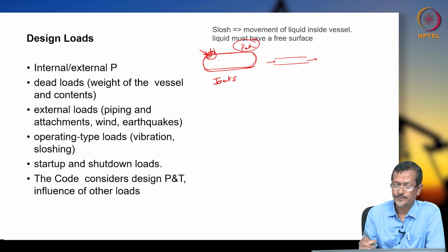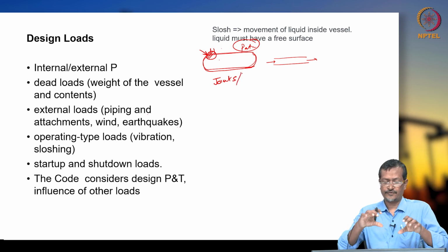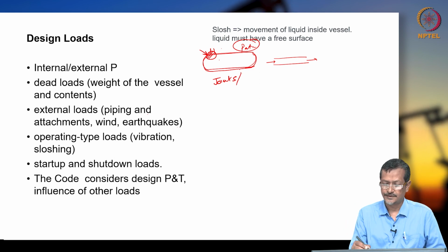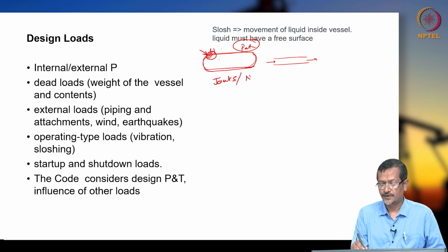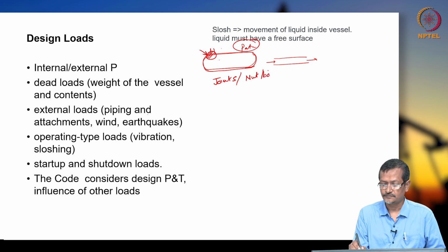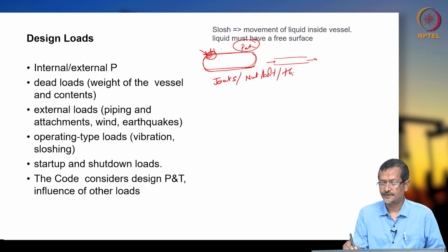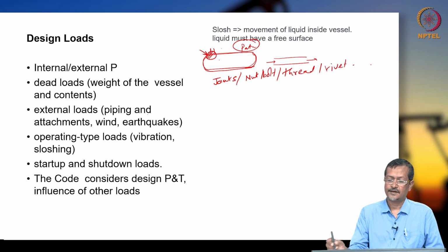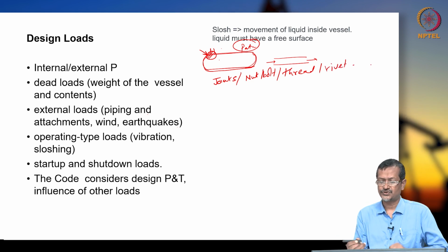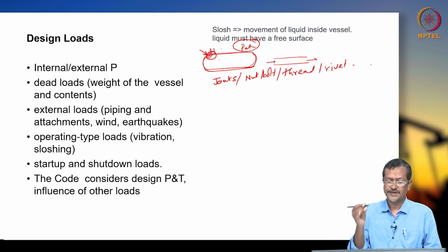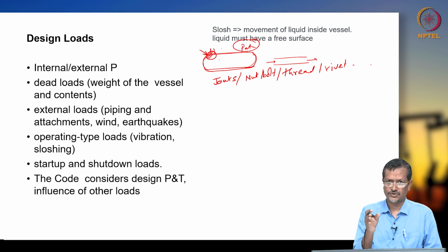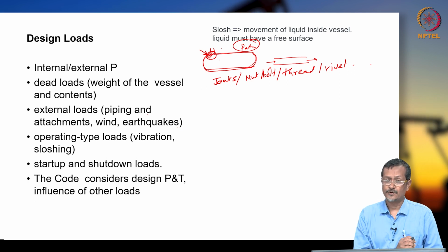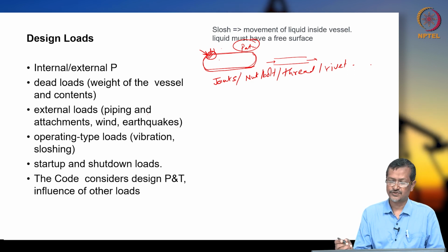Okay, joints will be the weakest point, because if a pipe fitting is there, the joint part will break first, then maybe nut, bolt, thread, rivet, cut, any type of notch. Because of mishandling, you get some small crack, notch, or surface scratching. That also will be the weakest point, because that will give stress concentration like this.